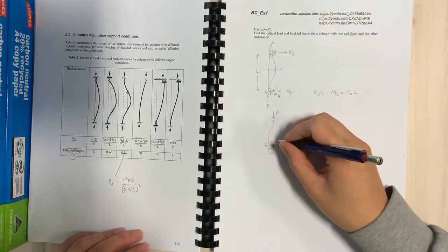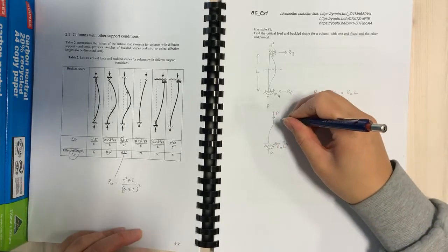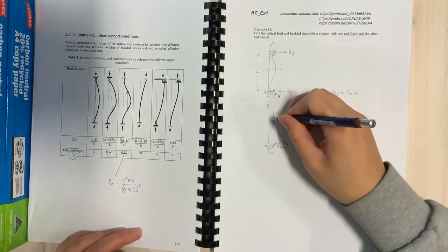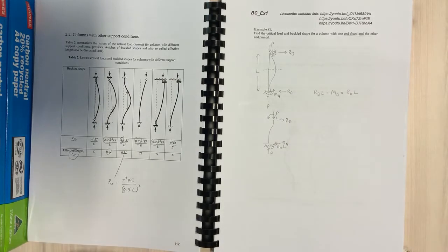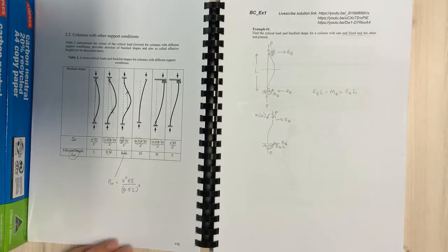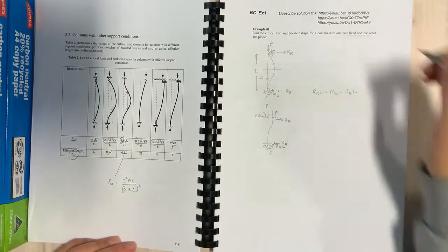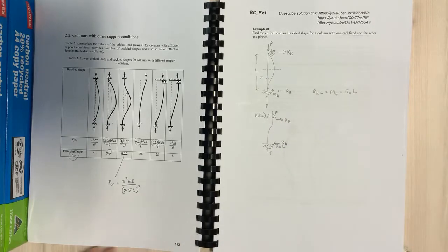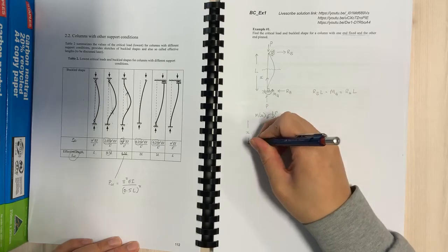So here we've got our RA coming down there, and then for equilibrium on this side here, we've also got RA. And then down here, again for equilibrium, we're going to have a moment at that point, and the bending moment there is going to be a function of x. And while we're at it, let's set up our conditions. X there as 0 going up to the total length, and then here that would be a distance x away from the supports.